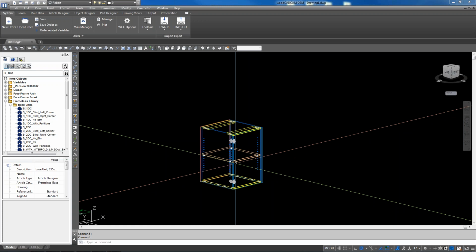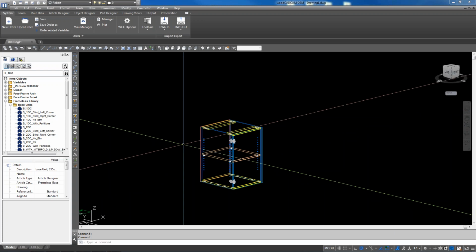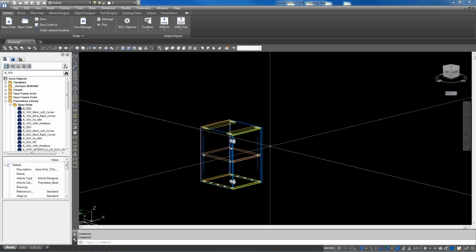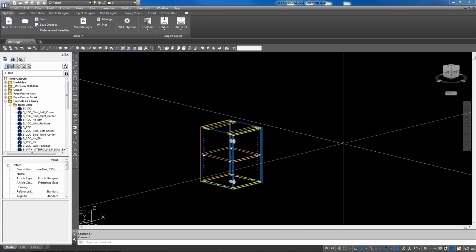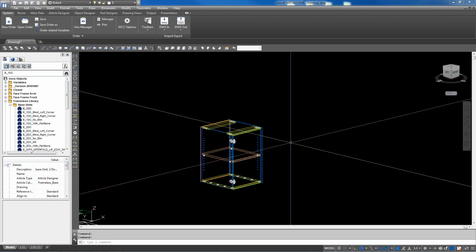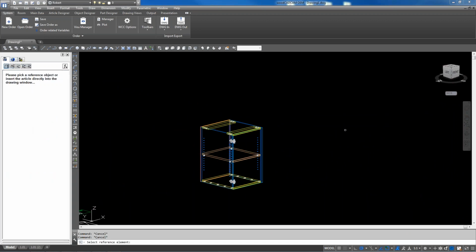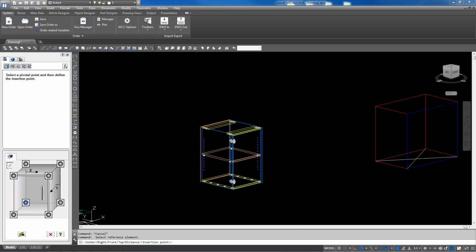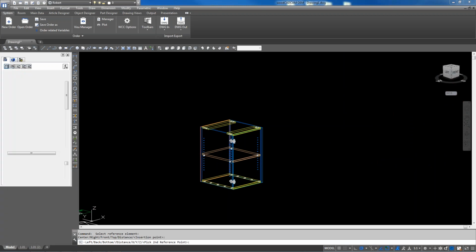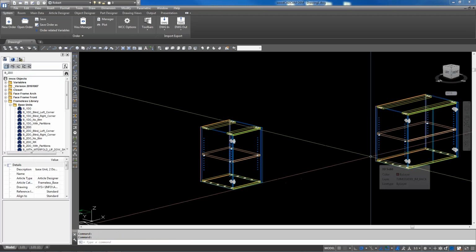Okay, where were we? We were swapping cabinets. So the replace only works like this: you can replace any cabinet you're drawing with any other cabinet you're drawing, but it takes on the properties of the other cabinet. If you want the size to match, you have to adjust the size of whatever you're using for the replacement.